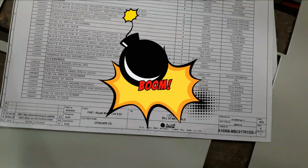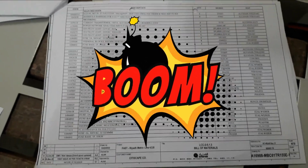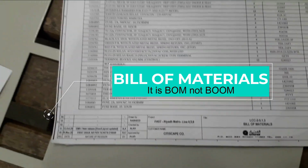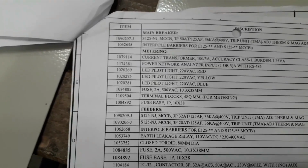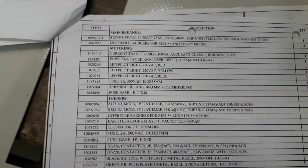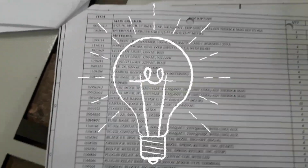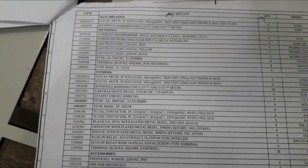This is what we call the BOM, bill of materials. You will find here all components installed inside the panel. For example, the main breaker: S125 NJ MCCB, triple pole, 50 ampere, 125 ampere frame, 36 kilo ampere at 400 volt, trip unit thermal magnetic adjustable.